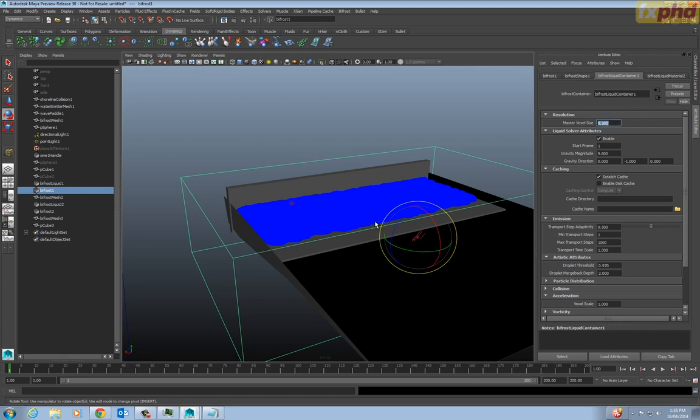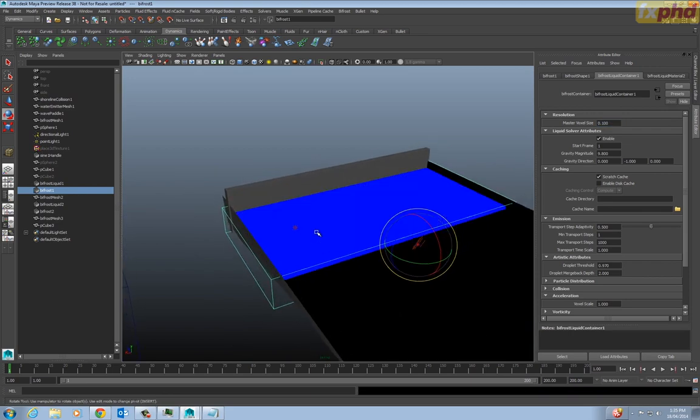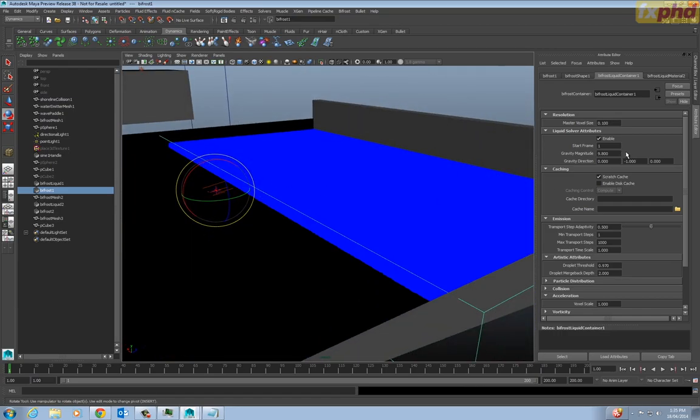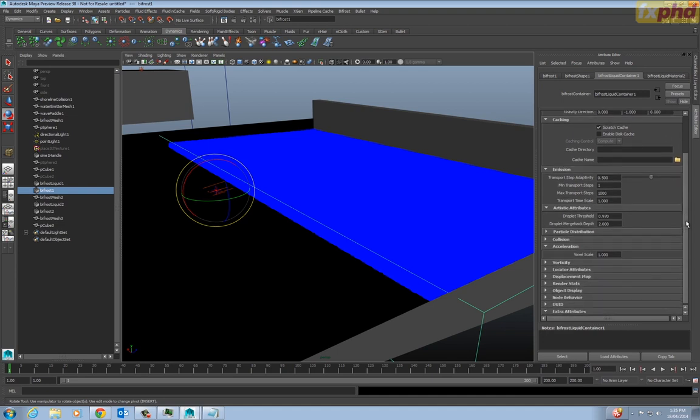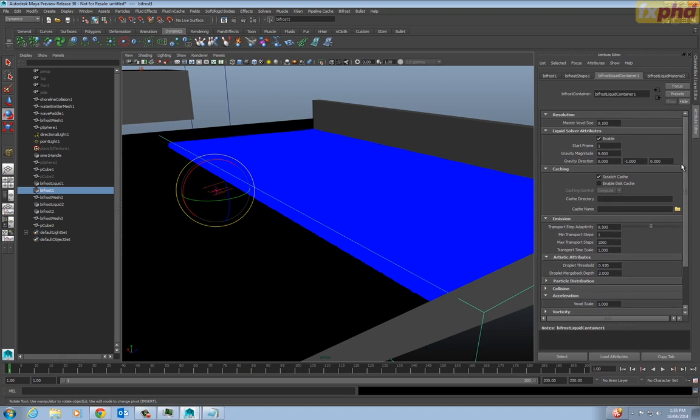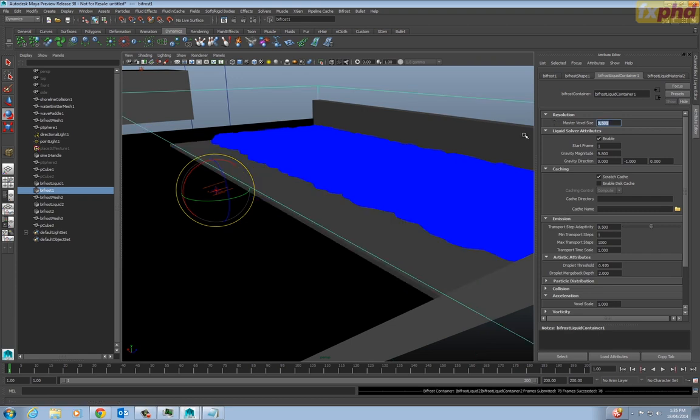So at the moment we've got master voxel size 0.5. If we change that from 0.5 to 0.1, when that updates, you see that you have a much finer, much more resolved water surface. We can straight away see that that's gone from Play-Doh into a liquid, a very thin, detailed liquid shape. It does take longer to simulate, but you have to set that correctly. Otherwise, you won't get the right behavior on your liquid. If we turn it back to 0.5, it's just too blobby.